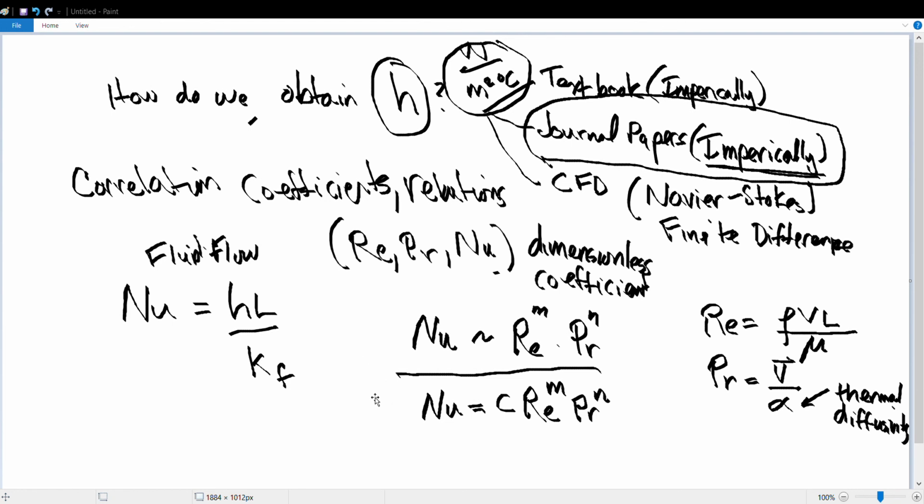And again, the heat transfer coefficient is what we use to solve a problem. In our case, if we're doing this for flow over a hot surface, for example the air sterilizer, the heat transfer coefficient is what we use in the convection equation at the beginning of this lecture to determine what the temperature rise of the air over a hot surface is. All right, and so you might want to go through some of this information here.